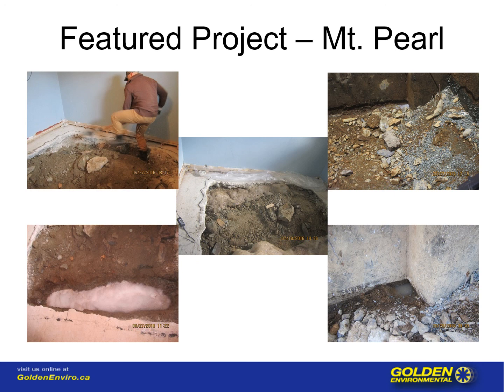This photo shows the inside of the wall adjacent to where the oil tank had been sitting. Again, the concrete floor was dug up for easy access. We did also inject the microbe component, so this was advantageous. You can also see in the bottom left-hand side the BIM 200 surfactant that we were using to flush the foundation wall with, the outside concrete brick, and the weeping tile. So there's great access there. We had a great saturation with the BIM 200.